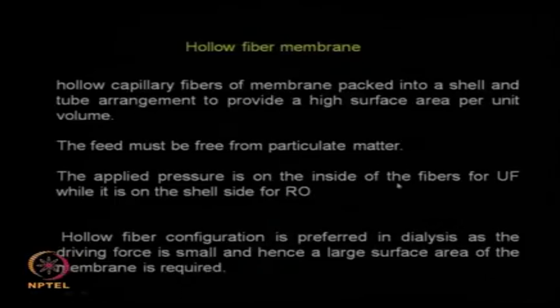If you have an ultrafiltration, then in the hollow fiber the pressure is applied on the inside of the fibers. So that is the driving force. But if it is an RO process, then the pressure is applied on the shell side, that means on the outside.